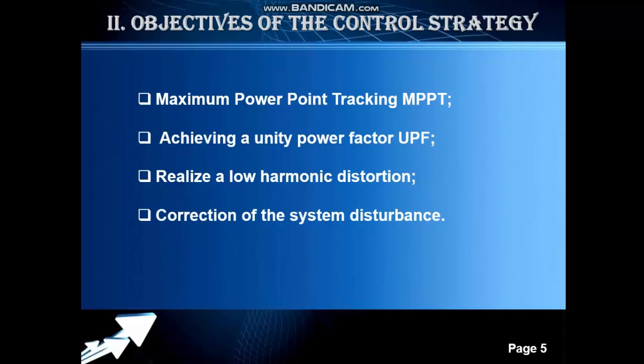And the most important point in this work is to develop a control able to realize all the aforementioned objectives in presence of system perturbations. We are speaking here about parameters disturbance of the system and harmonic pollution of the load current. This point has never been treated in any research. If we use a higher switching frequency, the harmonic components will be pushed to the higher frequencies. So, we can filter out the harmonics by using a simple pass filter with a cut frequency near to the fundamental frequency.